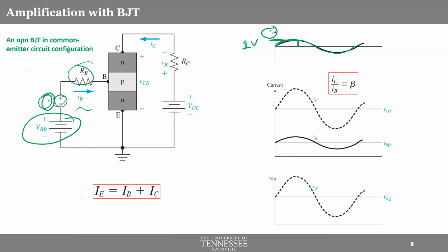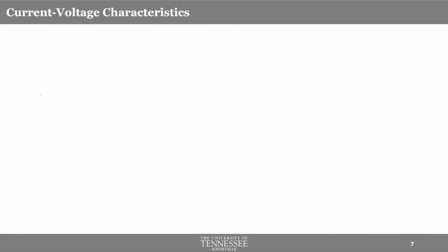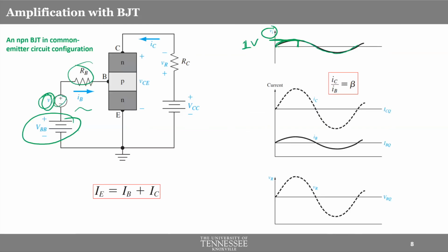Remember, in the previous circuit which we talked about here, we didn't have any AC source, but we still had IB, right? You have a DC voltage and resistance, you'll have a DC IB. So here as well you have a DC IB, but on top of that you have an alternating part as well. So if you try to plot IB with respect to time, if you only had a DC component, DC voltage, then IB would have been like this, straight line, DC.